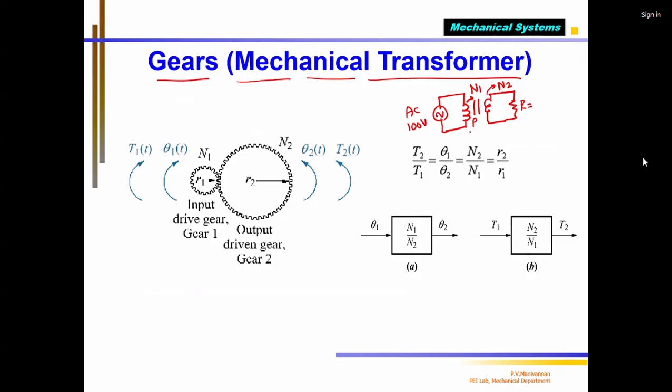Now, once you supply voltage to the primary coil, the circuit is closed and there's a current flow. This I call VP, and this voltage is VS. Because of VP, there's a current IP flowing in the primary coil. Because of that, the transformer generates magnetic flux, I say phi P. This magnetic flux will link the secondary coil also, so it is going to cut it.